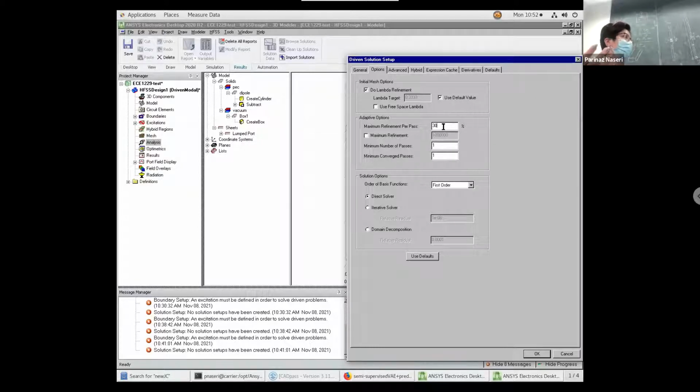It's the same thing here. Let me show what I mean by mesh cells. Let me go with a square, for example. Like this one. This is a square. HFSS, let's say, starts from a very easy case. It never starts from here, but it starts with RWG or triangular mesh cells.